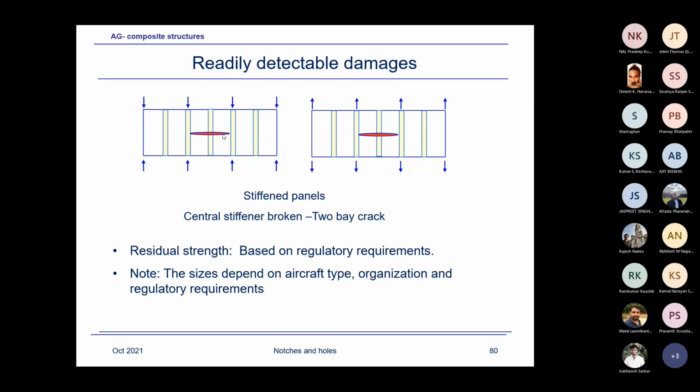Compression strength mainly depends upon the shear modulus capability of the matrix. On one hand, in order to improve the impact damage tolerance of the composite, we use toughened material with higher toughness of the resins. That's perfectly fine. It does definitely improve the impact damage tolerance. Impact damage resistance, in fact, I would call it, rather than tolerance.